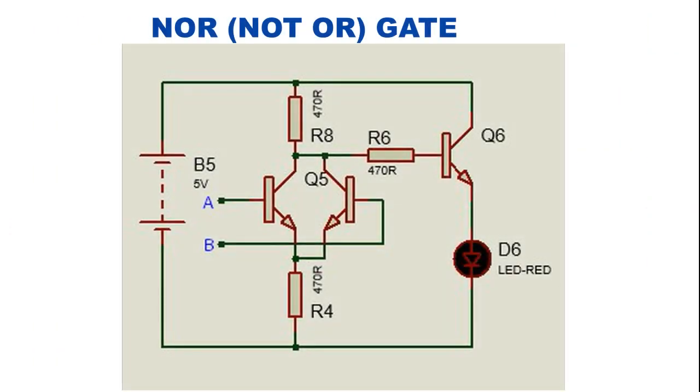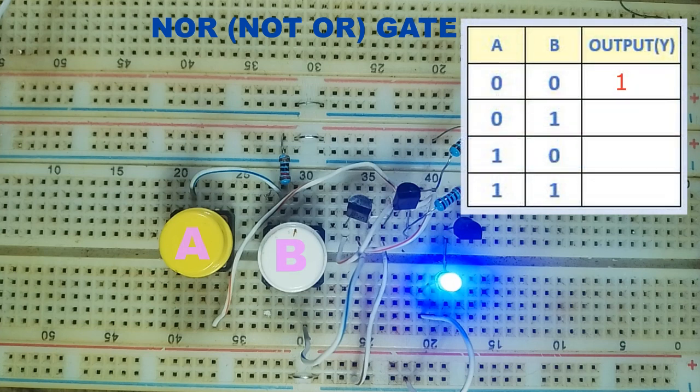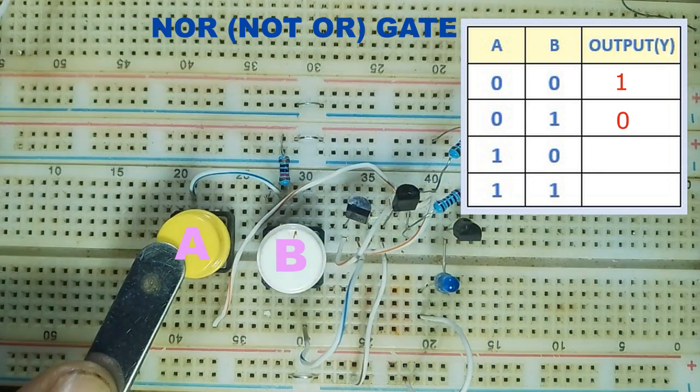NOR gate. This is an inversion of the OR gate. We achieve this functionality by passing the output of an OR gate through an inverter, which is implemented using the 3 transistors shown in the circuit diagram. As with the OR gate, let's build it and generate a truth table. The completed circuit on a breadboard should look something similar to this. As you can see, the inputs A and B are both 0 and the output is already high. Let's fill this state up in the truth table.